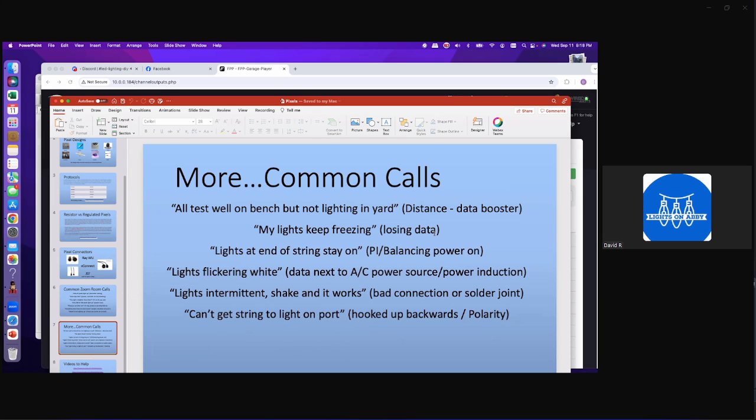I use them quite extensively, again, because I do long runs and I have a lot of extensions in my show. One thing to note is if you have a Pixa booster from Wired Watts and you use an F-Amp from Falcon, you'll get mixed results. For some reason, they don't talk well together on the same line. So if you have multiples like I do, I just got to make sure I grab Pixa boosters or F-Amps if they're all on the same extension.